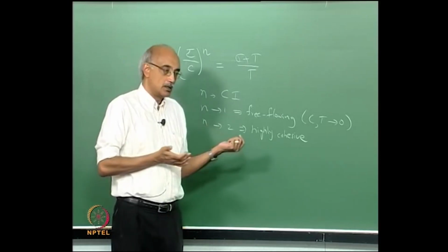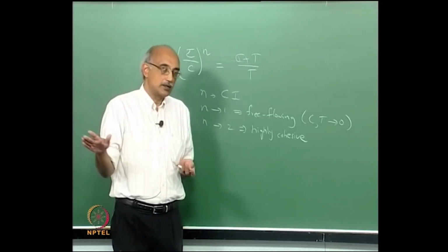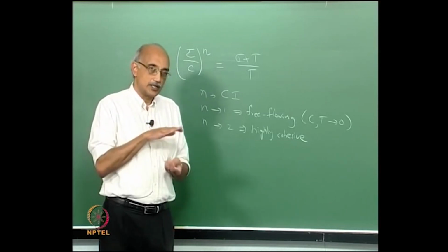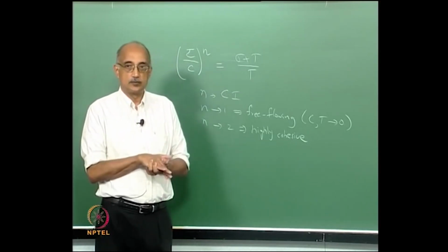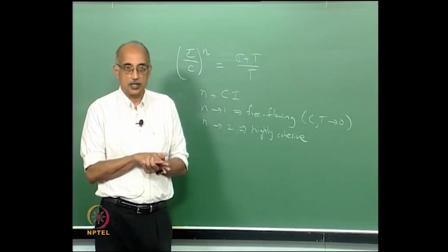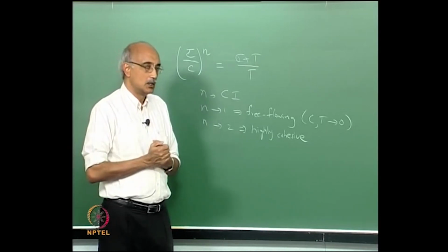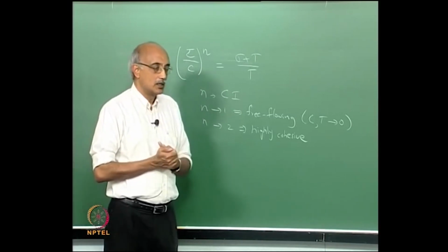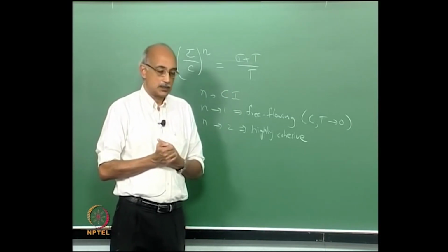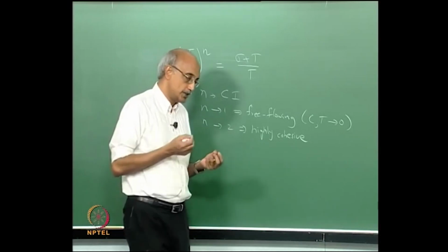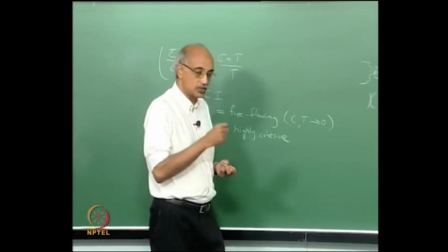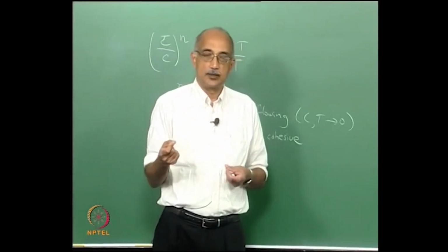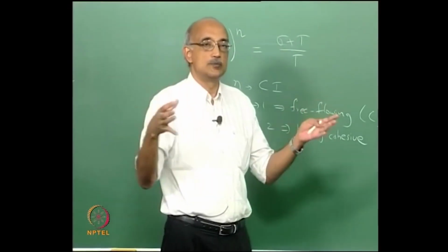So in this particular case, when you're discharging grains from a silo, is it advantageous to have a cohesive material, or is it advantageous to have a less cohesive material? Less cohesive? True in general, but the advantage of cohesive flow is in this particular case it's more predictable, right? I mean, because it acts like one huge mass essentially.